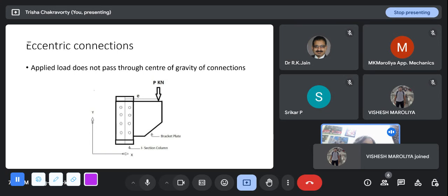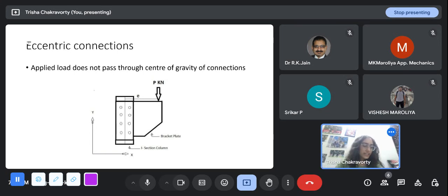Okay, one of those questions was: why do we use Fy, that is yield strength, in the design of butt welds, and Fu, that is the ultimate strength, in the design of fillet weld? In limit state design, technically we should be using Fu in both cases, because the whole point of limit state design is that we exploit the post elastic behavior of the structure as well.